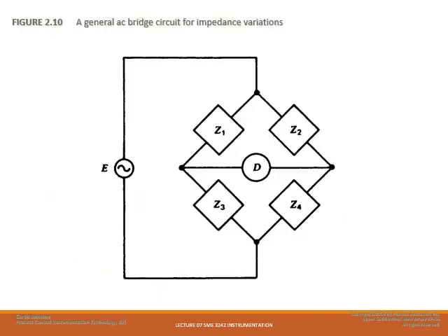As a summary, a Wheatstone bridge is a circuit that functions as a converter that is able to convert any impedance variation into voltage. So you're able to convert resistance to voltage, or capacitance to voltage, or inductance to voltage. The arrangement is the same, the equation will be the same, only the difference is the impedance value.